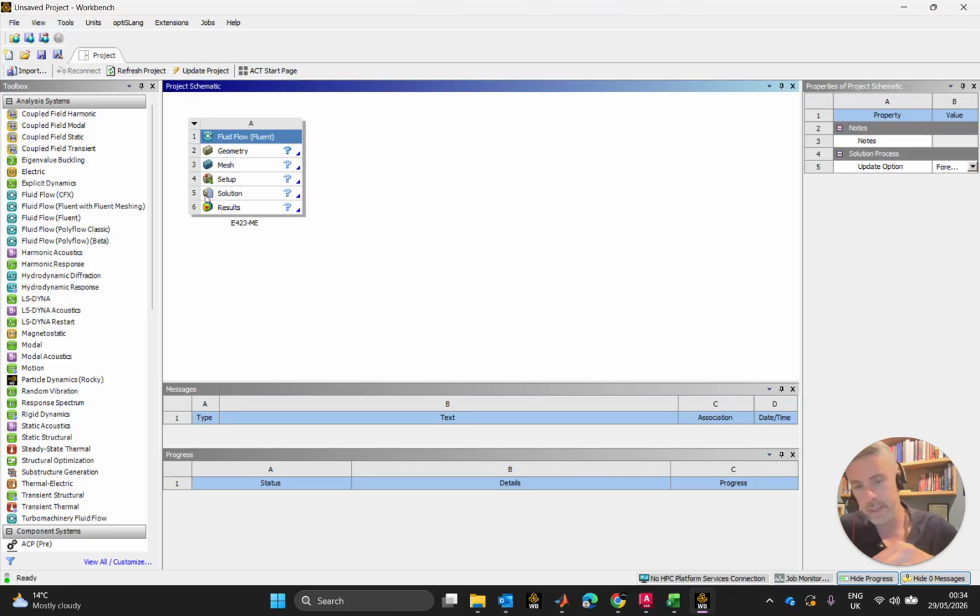So my idea here is that I'm going to do a CFD on a single element wing first, a main element made up of an Eppler 423 airfoil. And then, once we get an idea of the performance of that, we'll shorten that main element slightly with respect to chord length, and we'll add on a flap. We'll check that. And then we'll shorten two of them and add on a second flap and check that. Our objective here is to get an appropriate amount of downforce onto the front wing.